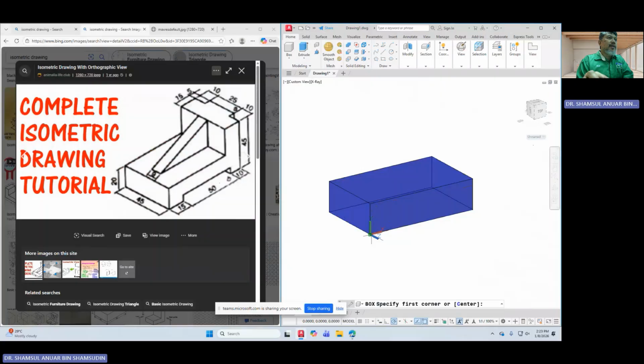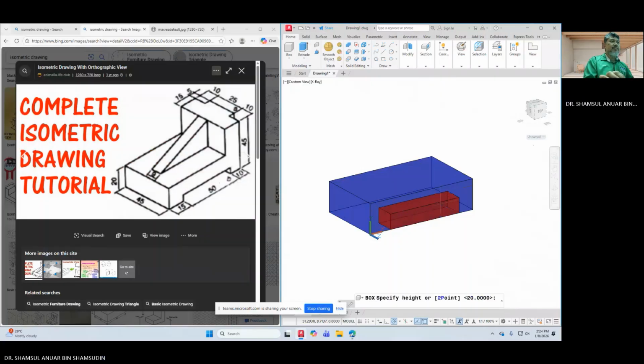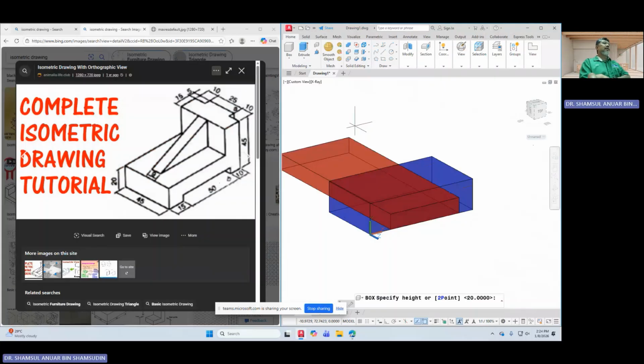From here, you want to start about this position, which is 15, and then from there is 50 and 10. So I'm going to use the @ sign and 50, 10, and then make that longer than you need.